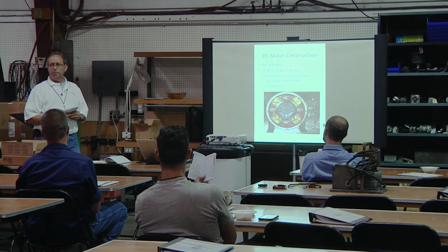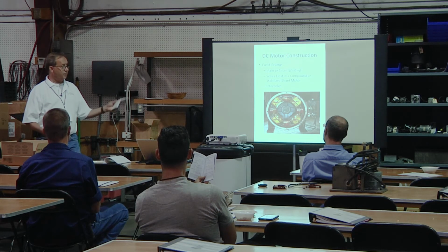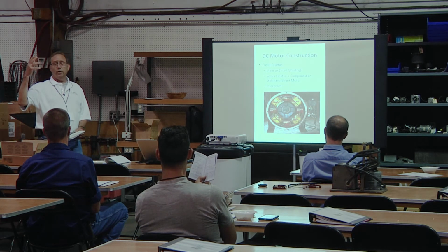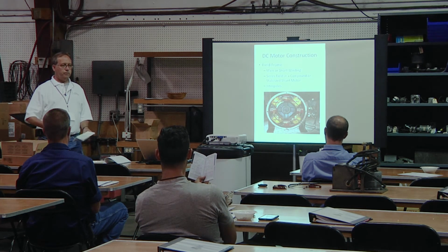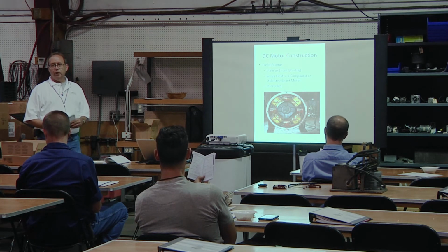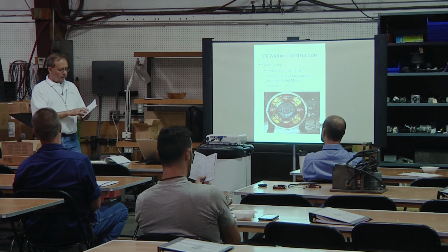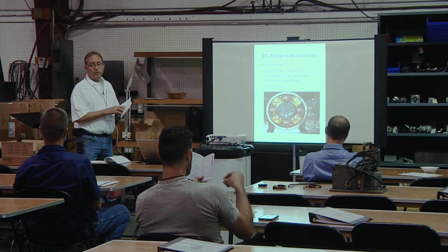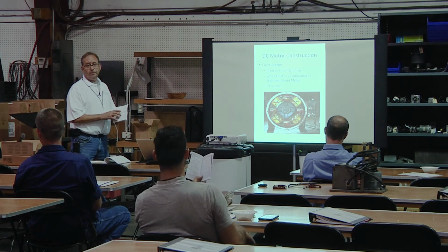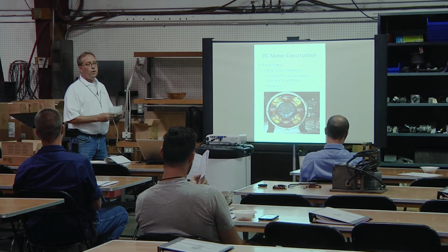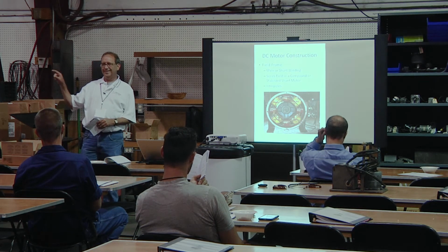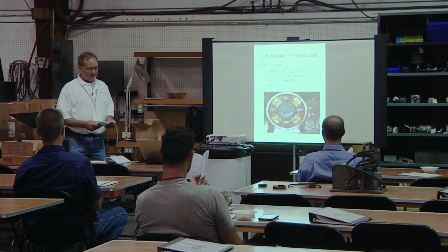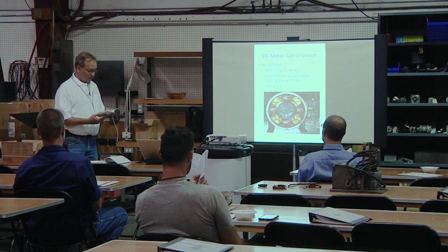You may run it no load, looks fine. Put a load on it, the higher the load, the less back EMF you got, because it's canceling out your back EMF, and the current just goes up. And you don't get it. A couple of load runs fine. So that's important. The only way to do it properly is by changing A1 and A2 and making sure that you keep the series field the same polarity as the shunt field. Or walk up to the drive keypad and change it that way, which is usually pretty easy to do.